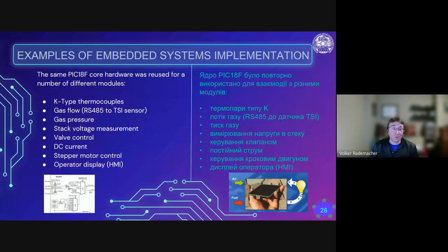How this DC current sensor was implemented in order to avoid the nonlinearities of a Hall sensor was basically in a magnetic core that was surrounding the DC line where the current was being measured. A counter electromagnetic force was generated.